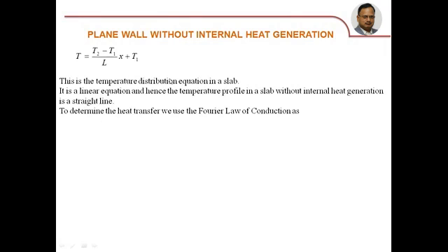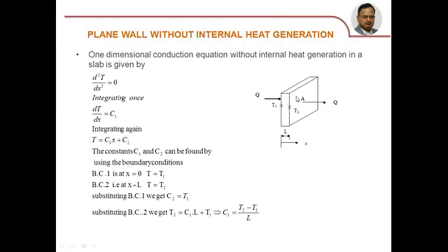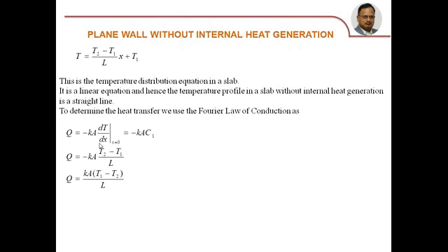And now this gives only the temperature distribution equation in the slab, but how to determine the heat transfer? Follow carefully. The heat enters the element at x equal to 0 and it leaves the element at x equal to L. So the conduction heat transfer starts at x equal to 0 and ends at x equal to L. So we use that condition.